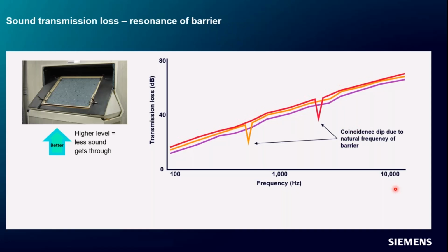If you have a very large wall, you need to consider that that is basically a big plate, right? And it's going to have its own natural frequencies where it wants to bend back and forth. And just like our expansion can had a natural frequency where it liked to oscillate, any wall will have a natural frequency, but if the wall gets big enough, that might drop into a frequency we care about, where all of a sudden, in this orange line, there's a drop in the transmission loss because right here at 800 hertz, that's where the barrier wants to oscillate in a bending mode, and it actually helps the sound get through. So you'll sometimes see these dips in transmission loss, and they almost always have to do with some sort of resonance of the structure or the acoustic volume for something like a duct.